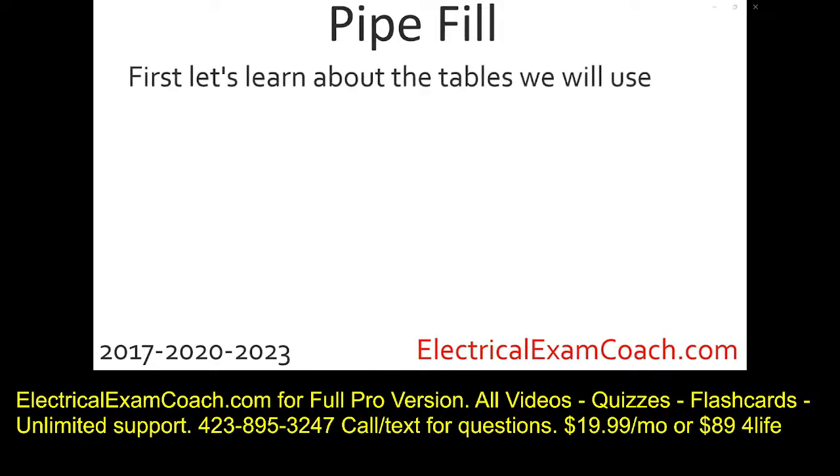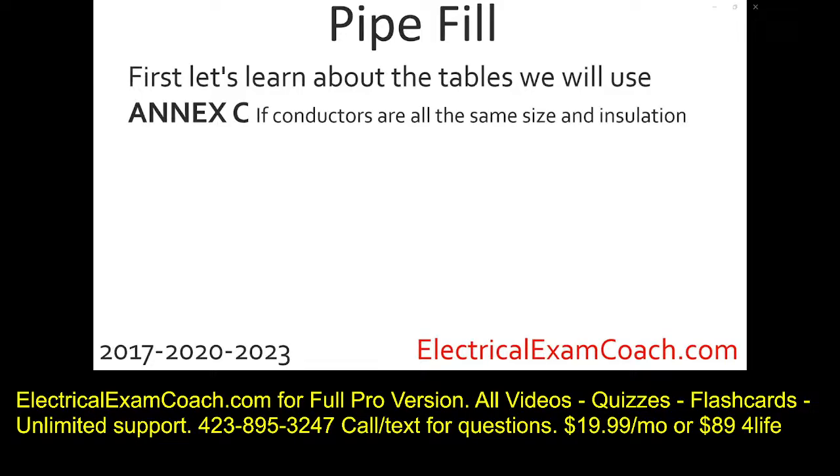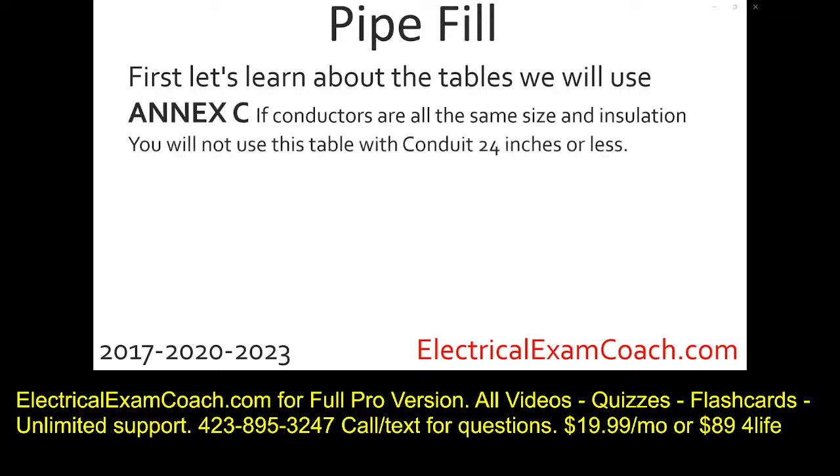Let's go ahead and learn about the table that we'll use if they are all of the same size. We're going to use Annex C. And if you've tabbed your code book, you have an Annex C tab. And if you haven't tabbed it, you can just follow along. If the conductors are all of the same size and insulation type, we get to use like a cheat sheet in Annex C. It's one of my favorite tables in the code book. You will not use this table if the conduit is 24 inches or less. Now, the code book uses the term nipples, but I want you to imagine in your mind, anytime the conduit is 24 inches or less, you're not going to use Annex C. You're going to use the method that I'll teach you in lesson 7.2.